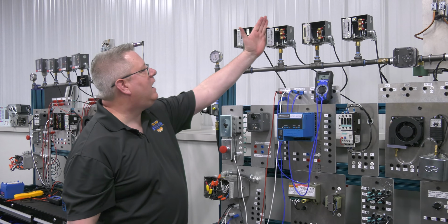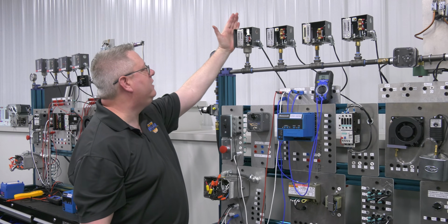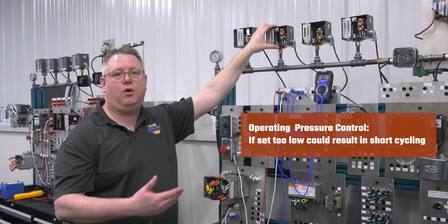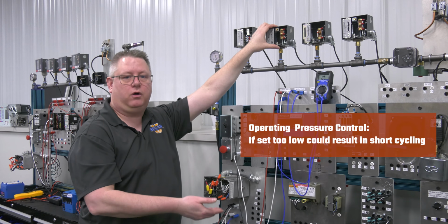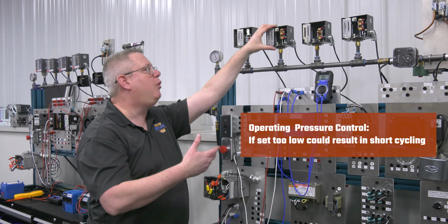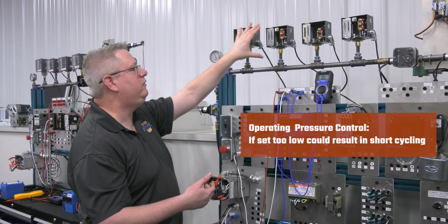So anytime we're going to adjust or look at this, we need to make sure it's coordinated with our firing rate control. Because if this is set too low, we may not attain low fire with the firing rate control before we shut off. And that can result in short cycling. So that's an important reason to verify the relationship between these two settings.